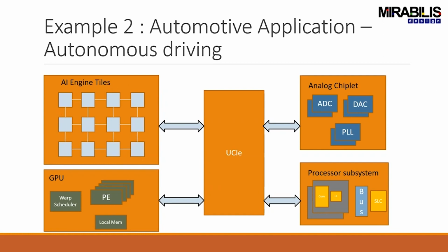Similarly, right over here within each of the engines, or maybe a common one, there could be a local memory there as well. So you're looking at not just the UCIe backplane, but also the bandwidth, the throughput, the latency, the power consumption, and also the configuration and the topology, all of those, both within these different dies plus the die-to-die communication. When you looked at the earlier one, the multimedia, everything was pretty much self-contained within its original dies.